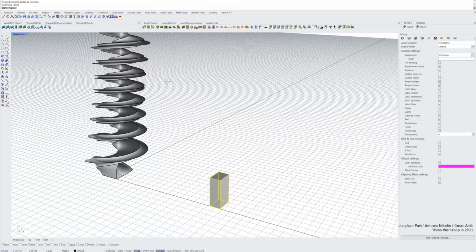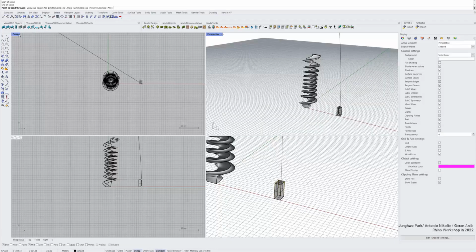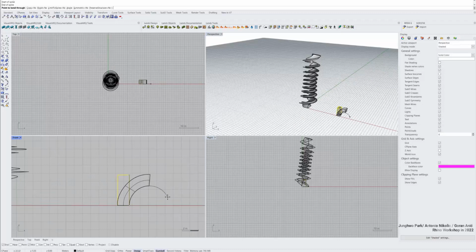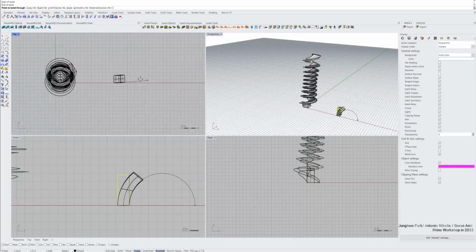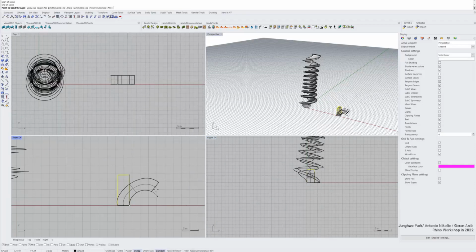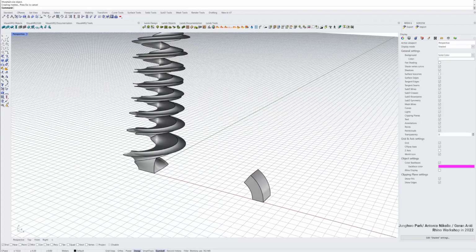Next one is bend. Again, you can set the spine, and then if we double click on the view, you can choose where to bend it, from front view, right view, or even top view. Once you bend it, you have the bent object. Simple. That's bending, and there's also taper, which is not that interesting.